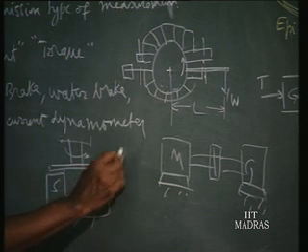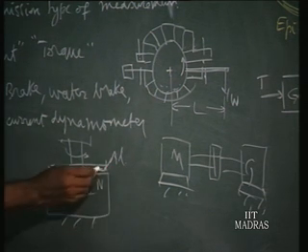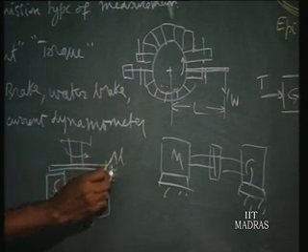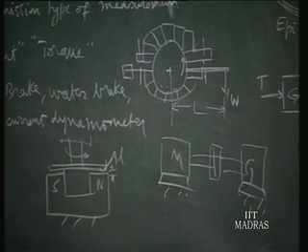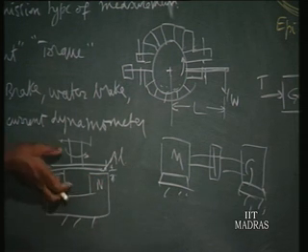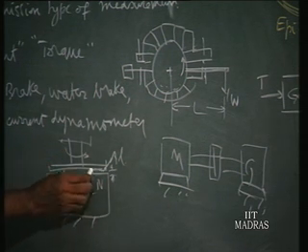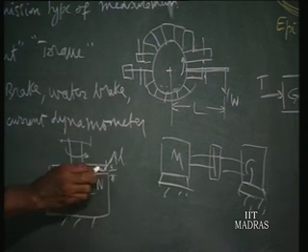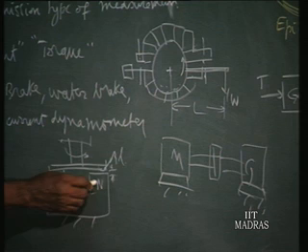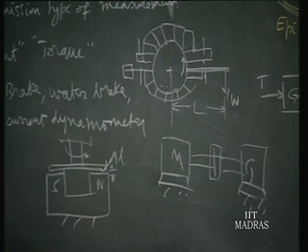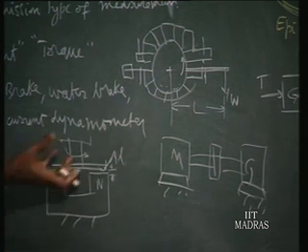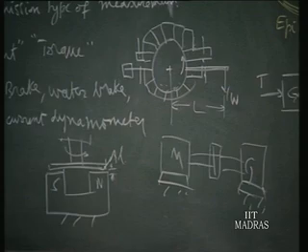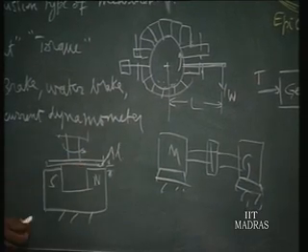So for example, an aluminum disc is rotated, and by changing the distance between the rotating disc and the permanent magnet, we introduce a different torque on it. When a metal rotates in the vicinity of magnetic lines, eddy currents are produced, and these interact with the main magnetic lines, so a torque is there opposing the rotation of the disc.